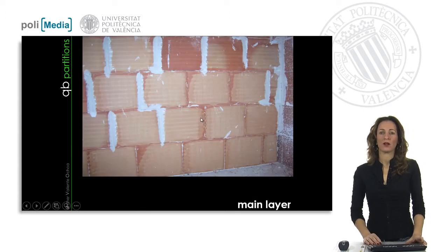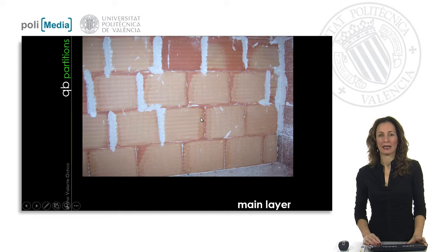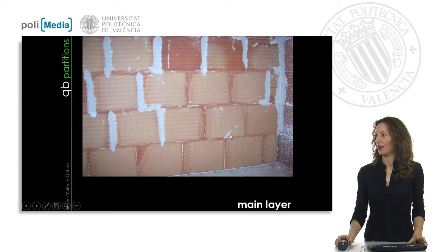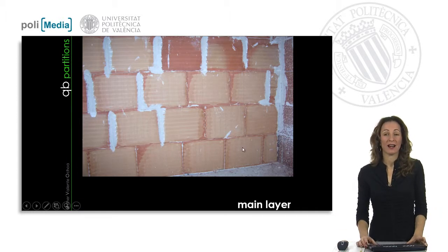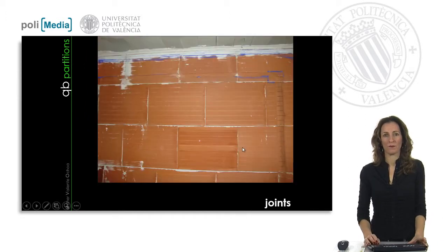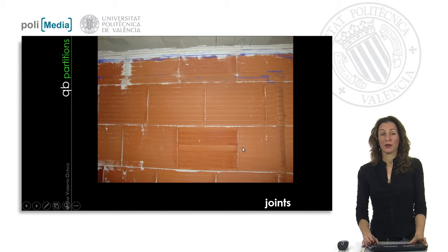In some cases we are going to use special pieces, like this big size brick, which we are going to place in this wall. These big size bricks are very useful, but on the other hand we have to consider the final resistance of this wall. In the joints we can pass all the future building services.